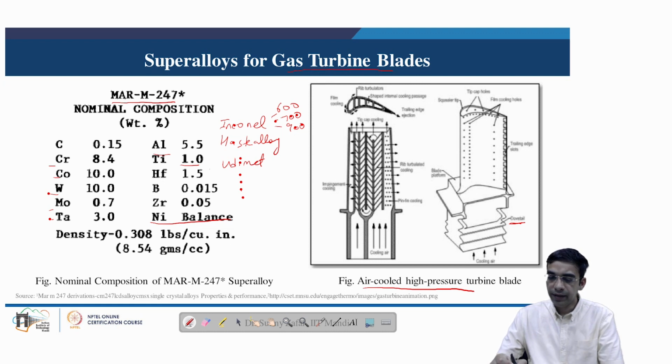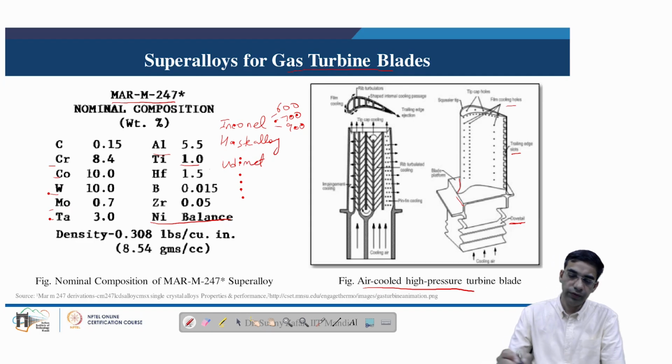On top of it we have the blade platform, and on the blade platform we have the actual blade as shown here, and the cross section of the blade is aerofoiled as you can see. And the blade also has certain slots and holes which are known as film cooling holes, present to enhance the surface area for cooling by the incoming air. So we can understand when we have this type of a complex product, which is of course operating in complex operating conditions of high temperature, oxidation, and so on, we have chosen a material which is known as nickel based superalloy to manufacture such blades.